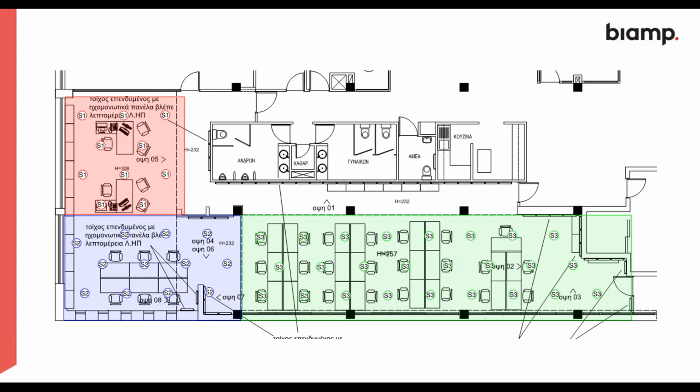Johan has asked about the cable length limits when patch panels are in the chain, with usual structured cable runs and patch leads. If we're using an existing site with patched cables in, then we have to take the patch cable or the structured cable as part of the length of the run. So that sometimes does limit the number of emitters that you can use on a system in that space.